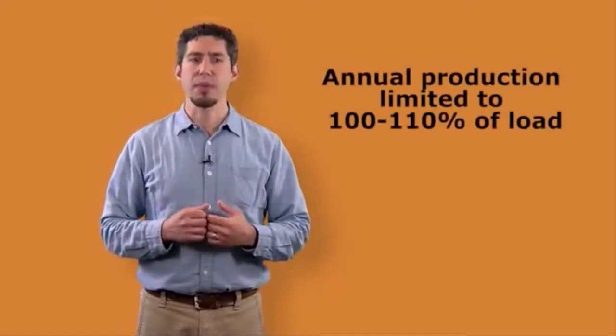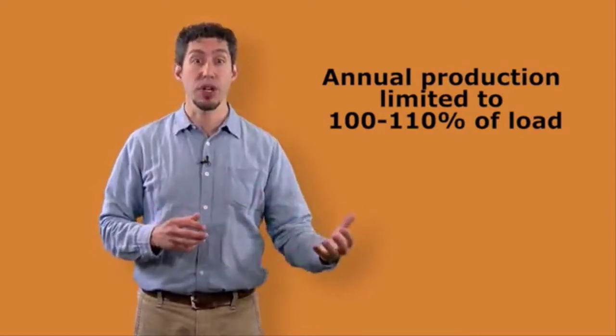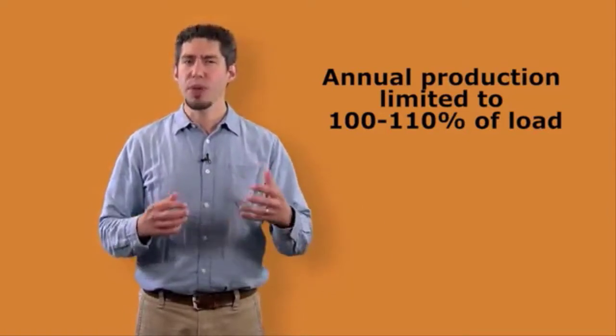There are also oftentimes both financial and electrical limitations for producing more than 100% of the electrical need. You can't produce more power than your electrical system can accept, and several states limit the payback on production to no more than maybe 100 or 110% of your annual electric load. Otherwise, you end up being what's called an independent power producer. So review your federal, state, and local rules to know your maximum allowable photovoltaic electricity production.